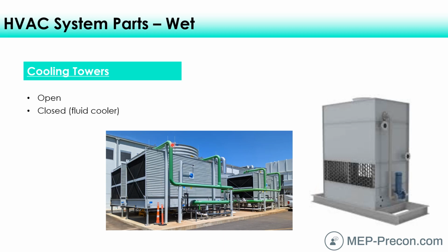It's usually an axial fan, because why? Axial fans are good for moving a lot of air through not a lot of resistance, not a lot of static pressure. And there's not a lot of static pressure within these units, not like a long duct run. You could have a centrifugal fan, but it's usually most common to have an axial fan at the very top of this. And so we're going to force evaporation at a very high rate. We're going to force basically just wind across that water to evaporate it.